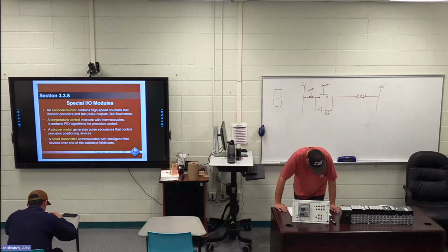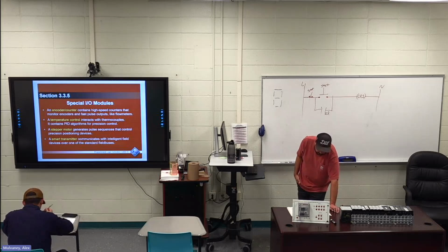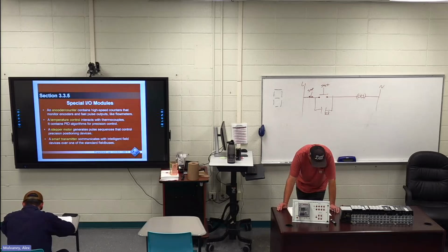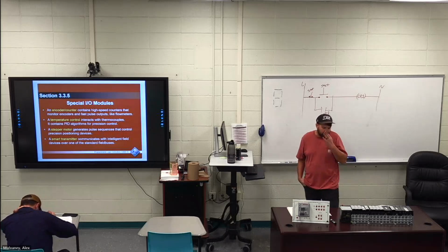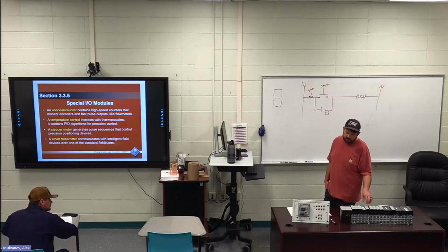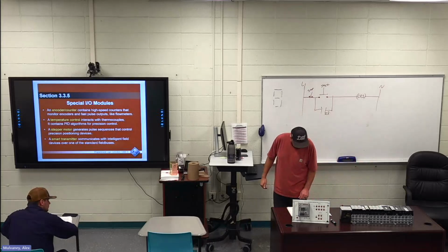Flipping over to page 18, I have the whole temperature monitoring controls highlighted. You need to note that the temperature monitoring controls is a special module, and the thing to key in on is the couple sentences right after where you see ADC in the bottom left. The numerical values for each input are processed by an internal microprocessor as an input to a PID loop. The processor executes a PID algorithm on each input. In module 10 last semester, you did PID controlling, but the math that actually does that is done in the special modules with thermocouples attached to them.